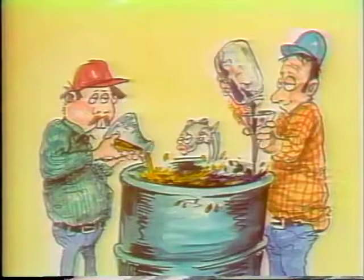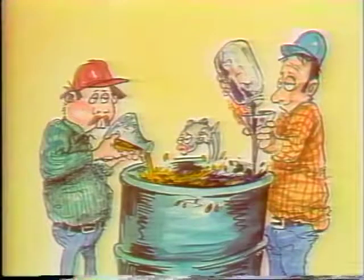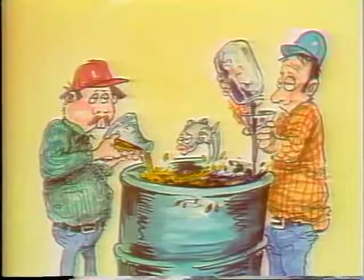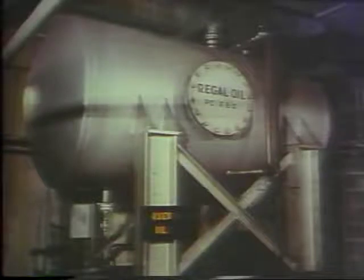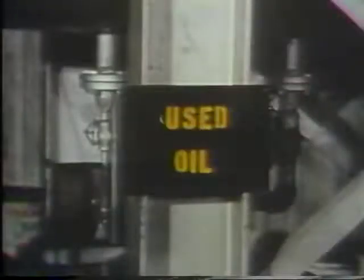Now, once you've removed oil from a barrel, never return it to its original container. If you do, you greatly increase the possibilities of contamination. Contaminated oil can cause serious problems because dirt and other particles could get into a bearing and scratch or otherwise damage its components. All contaminated lubricants should be clearly labeled and properly discarded or recycled.